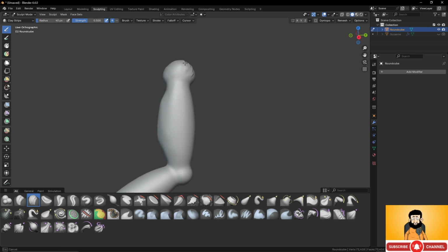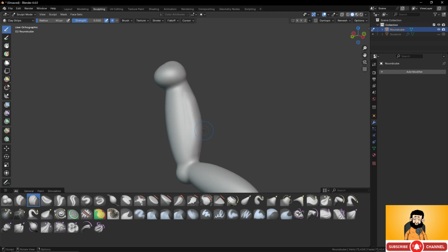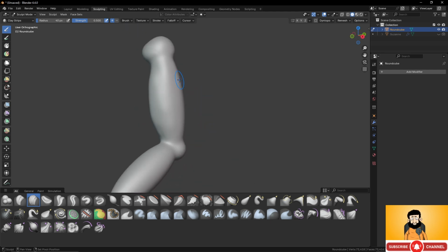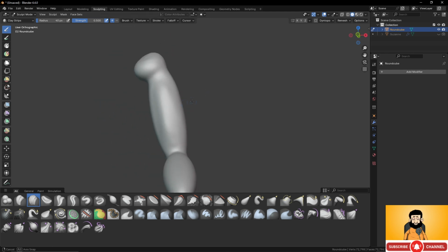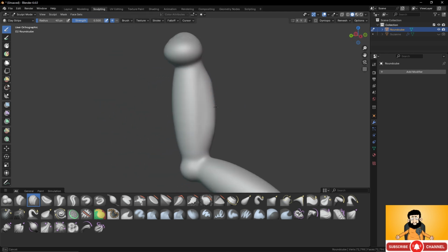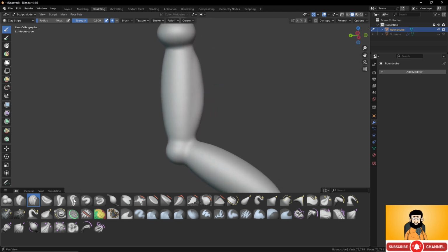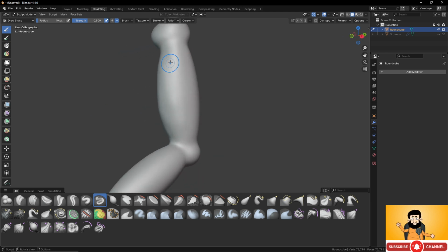Sometimes you need to change the level. Okay, so let's say for example here you want to increase the level, the global level. You come back and when you make a big change, like for example this, you just make a Control R, another one, and it will recreate the shape that you need and the new subdivision to play with. Okay, so it's quite easy to work with that, and that's why I really like to play with these settings here.